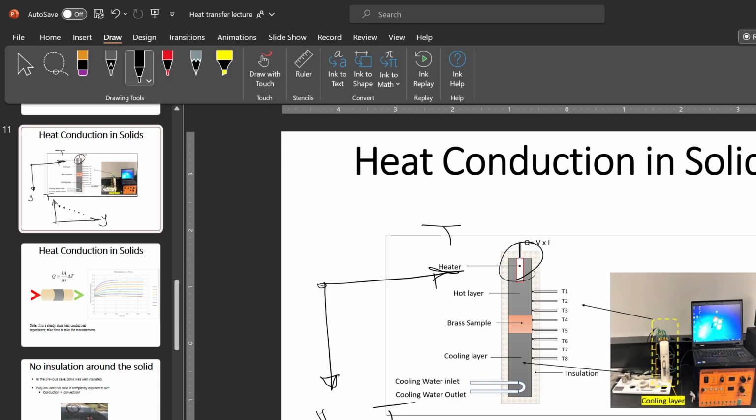Right? If the sample material is the same as the test setup material, then your temperature change has to be a line, right? And the slope of this line is the conductivity of the material, essentially, right? So using this data, you should be able to measure 1, 2, 3, 4, 5 conductivities. You can also take this temperature and this temperature, measure a sixth conductivity, right? Not just one conductivity. In theory, all of these have to be the same, right?